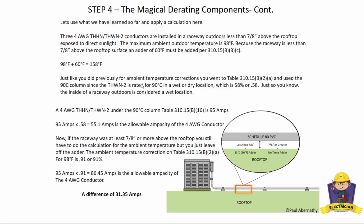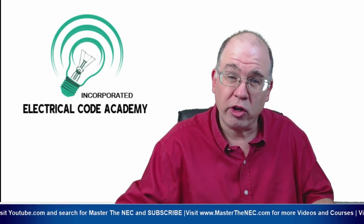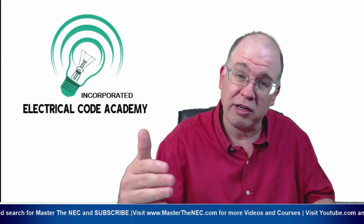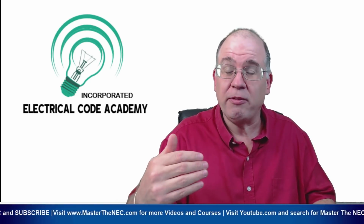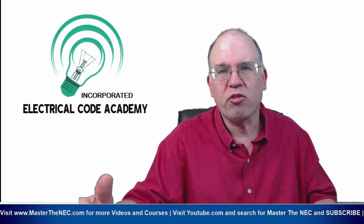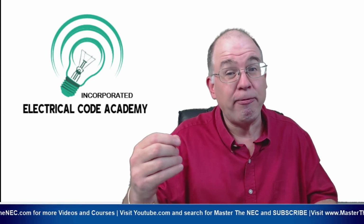And we already started in our example, which says we had a 4. But you have a nameplate rating on here. And most of the nameplate ratings on the air conditioning units, for example, will say a maximum overcurrent device and minimum circuit ampacity for sizing conductors, and then maximum for the overcurrent device. And you generally follow those rules. And they're all governed in 440 of the NEC, where we get those rules from. It's just the manufacturers will put this on a nameplate for you to be able to use. And so you get those values. So we're going to assume here that they did that and they selected a 4.